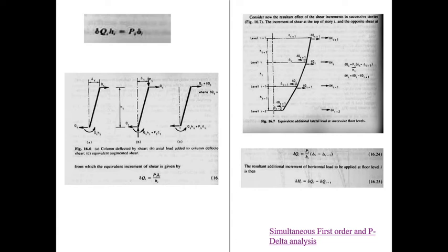Here also this procedure, as it is said, is continued till the displacements become 0. So a set of horizontal increments causes at any level of the structure the same additional movement as it would for the set of gravity loadings acting on the structure. Here it is Q1 H1 plus P1 delta 1. So this capital delta is the displacement here. So this is the displacement delta of i plus 1, capital delta. Small delta is the increment value in the shear forces.